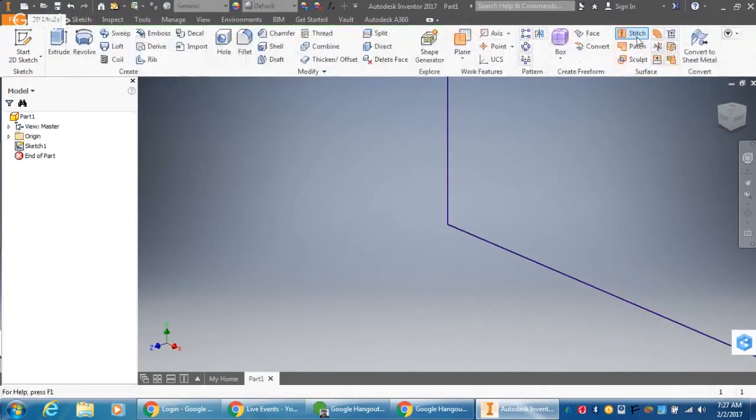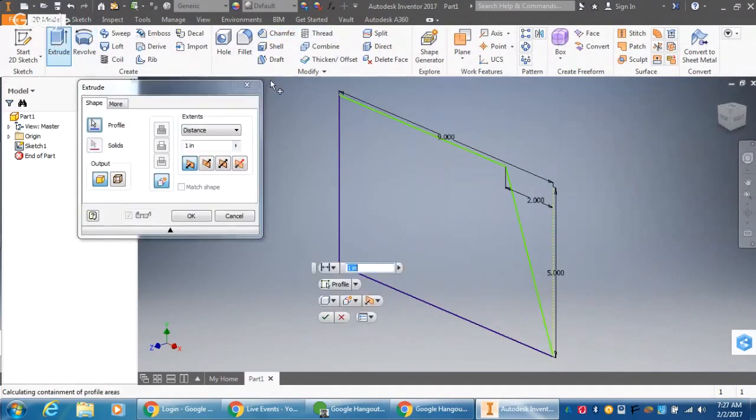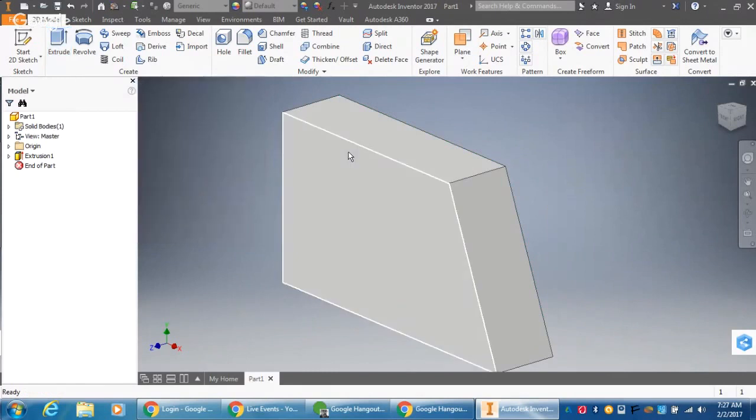So let's see. I'm going to finish my sketch, hit my home key, and go to extrude and see if it's going to, oh, no, we're doing good. All right, we're in good shape here. I'm going to extrude this 6. So I'm going to hit, you know what, let's do something a little different actually. Let's extrude this only 2. And we're going to build this just additively.